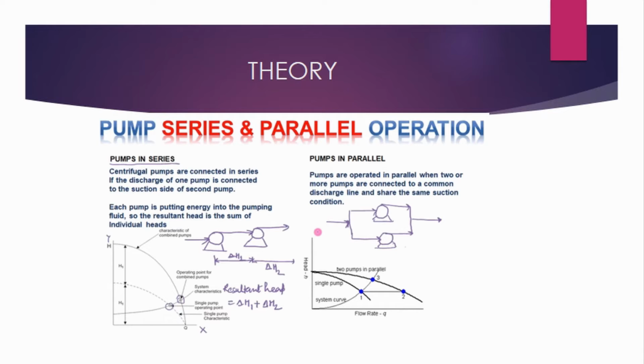Each pump in series will have the same flow, but the total head produced will be the sum of the pumps. When they are connected in series, each pump generates a head which corresponds to flow. The total head is the sum of head 1 and head 2, the heads created by the pumps in sequence at the same flow rates.